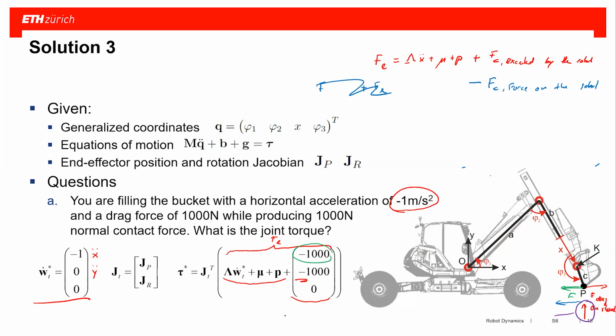That means I could make a selection matrix which selects this normal force direction. And then we have here the one which selects the tangential motion for the motion part, which is the one minus the normal force selection matrix. And what we have here means that here we have a force and here we have zero motion. So that's how the selection worked very nicely for the normal part.